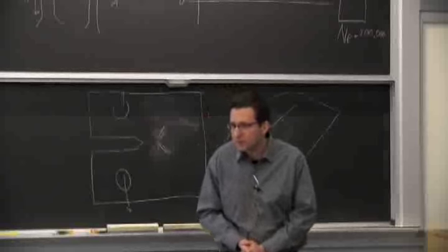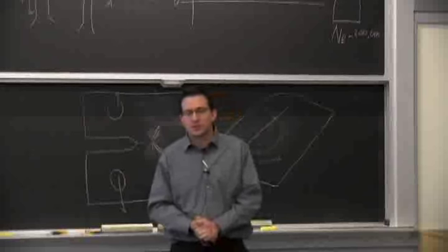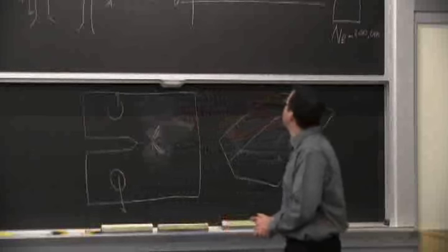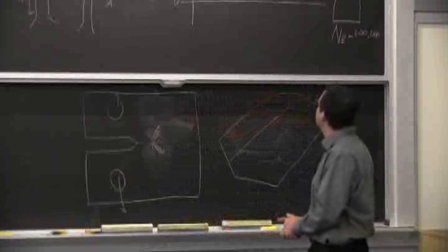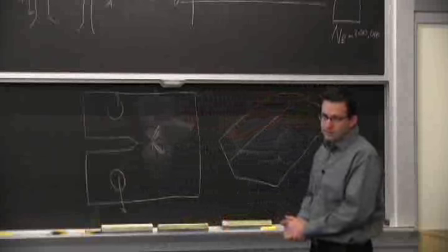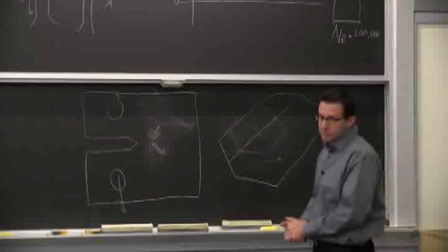Anything else? Yes? So on that, up there you have the stress amplitude and all that stuff. What stress is that? If I were to run an FEA model on something and I have loading case 1, loading case 2, is this going to be like max principal of one and then min principal of the other?